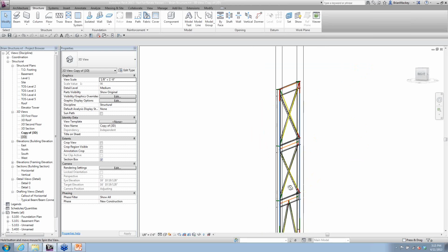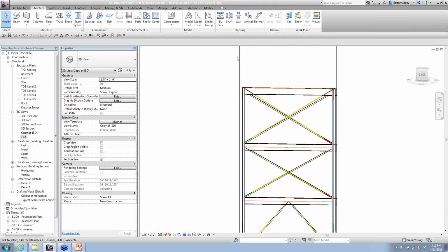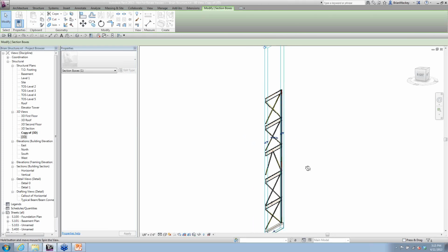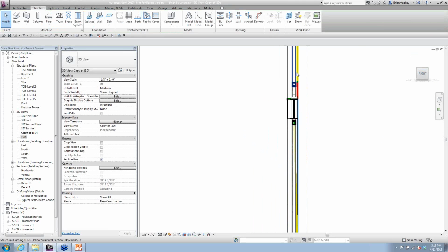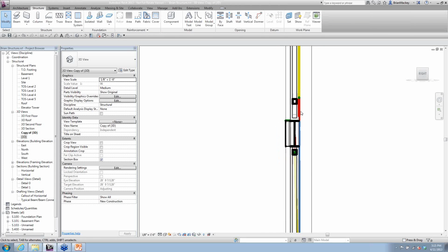You'll also see that when we got in there, we had the Y analytical adjustment. It's kind of hard to see here. Let me just pull this crop region in, or my section box, excuse me, in a little bit. So if I come over here to the side and start looking at this, now you can see my 3D objects are lined up to the center of these columns, but all of a sudden these are all bounced out way to the edges of the columns.